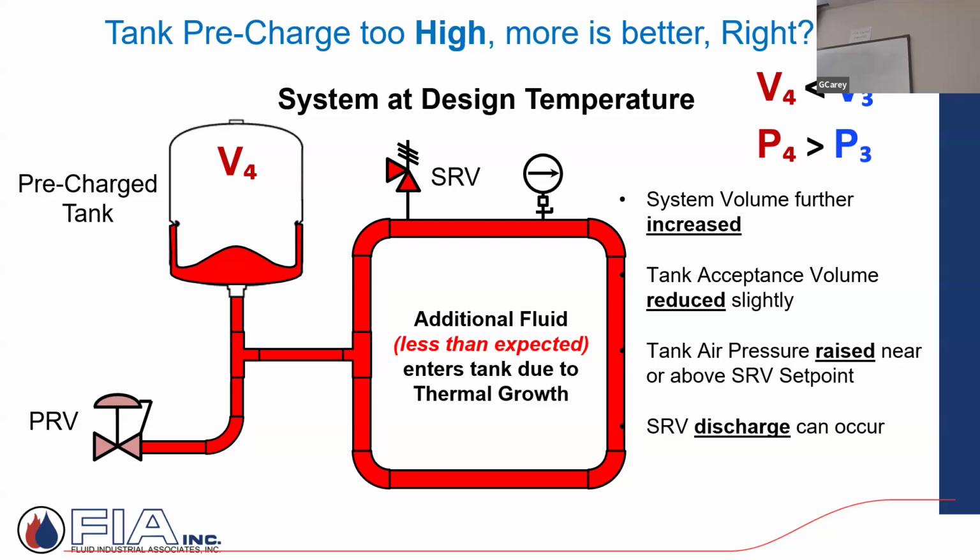There's a right charge. It's a function of the height of the system when it's cold, so that when you fill the system cold, no water enters the tank. And then as we get to these exercises on sizing the tank, we know that we've got X volume of water. And when I heat it to the maximum temp, I know what the expanded thermal volume is going to be. I've got the tank or tanks there to support it. And again, like I said at the beginning, when all of that takes place, these guys sit off to the side like they're not even there.